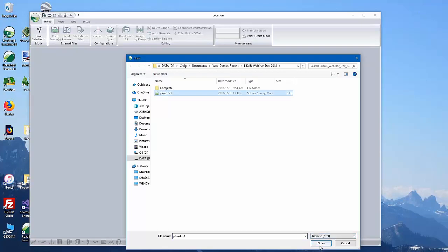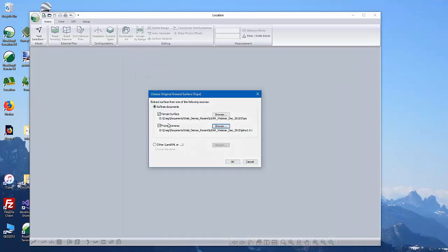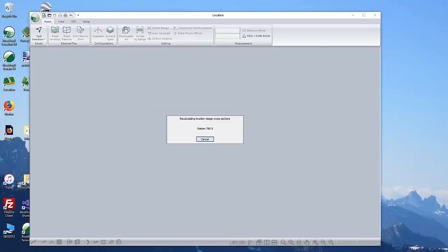So there you have it. You don't need to have a P-line traverse. If you were just pegging a road in, you just start up with a surface. But in this case, I've actually located the road beforehand. I've gone out, done a recce on the route, set up a P-line, a GPS to P-line. So I want to reference that in my final design. Just fire this up.